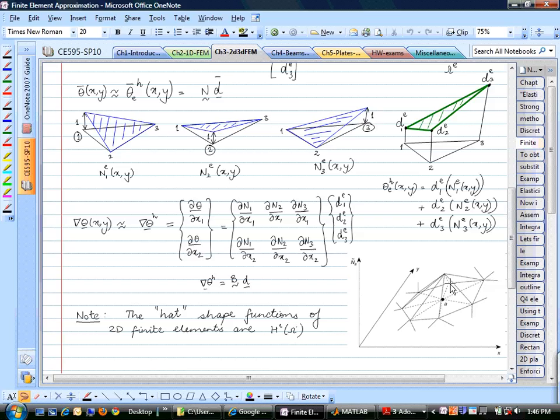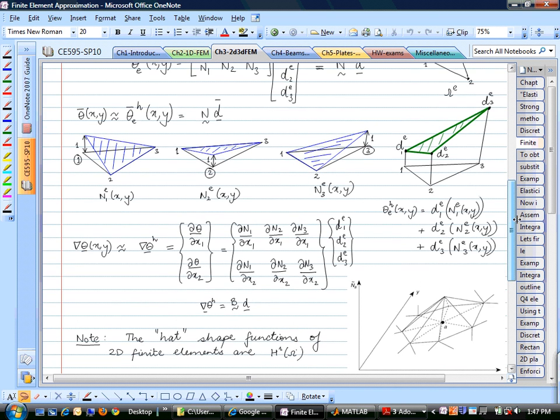And if I give you a picture with some shape functions for different elements, and I ask you to assemble them and ask whether this is a valid finite element discretization or not, you should be able to conclude that simply from the continuity. All we need is that on each and every edge, that function needs to be continuous. So if the function is continuous in 2 dimensions, it is a valid function to choose for your finite element approximation.